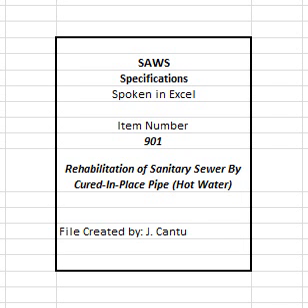7. Cleaning and television inspection. A. Before installing the new pipe, the existing sewer shall be cleaned and inspected per specification item number 866, sewer main television inspection, and specification item number 868, sanitary sewer system cleaning. Notify SAWS inspection department of any conditions which may prevent proper installation of the liner. All CCTV work will confirm active laterals and location.